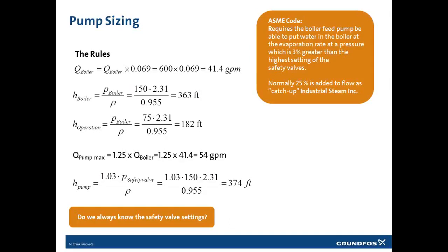And then the question at the bottom: do we always know the safety valve settings? No, we actually don't. But you must never size a feed pump before you know what pressure settings we are running at. It is not our job as pump producers or as pump distributors, sales guys, to inform about what is the pressure setting of a boiler. That should always come from the customer.